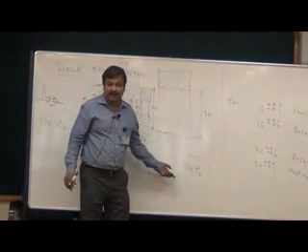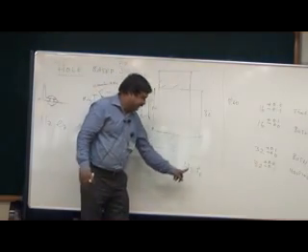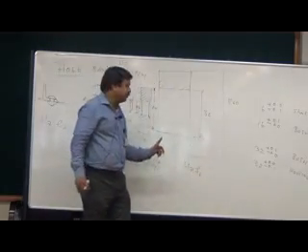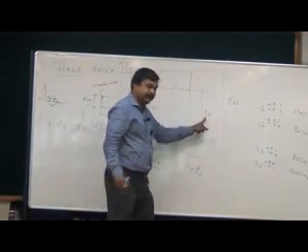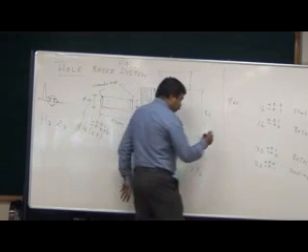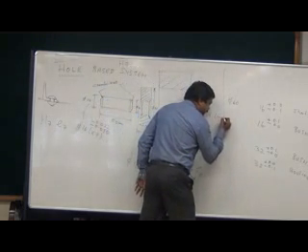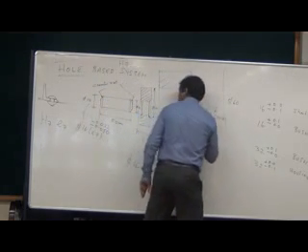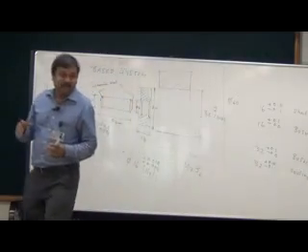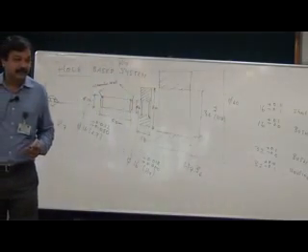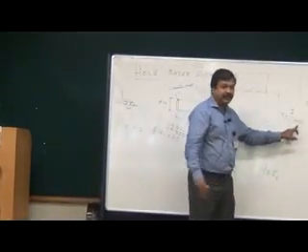H7 stands for what? Hole feature. S6 is going to be for the shaft. Where is my hole here? Here, 32 within bracket H7. Now how will you determine what is the tolerance? What are the exact values for H7?